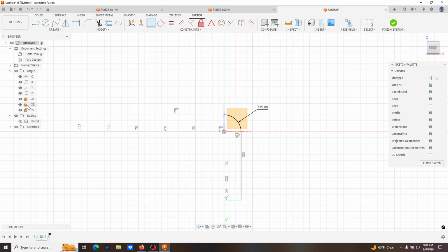But what I'd also like to do is just to make it visible. Let's see if it'll let me. Oops. There you go. Make that visible. If I could just grab this point here and see if it'll let me make it coincident to that. It will. So this is kind of nice in that I have my sketch here matched to this edge, and you'll see that it adds an automatic little projection line.